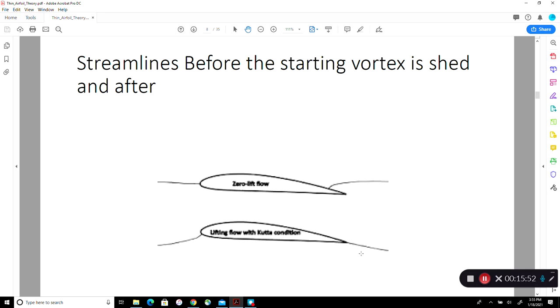Now we know there's a boundary layer over the airfoil. So when we say velocity magnitude, we are talking about the velocity field just outside the boundary layer edge on the trailing edge. What's above equals what's below, pressure above equal to pressure below, and the flow seems to leave smoothly.